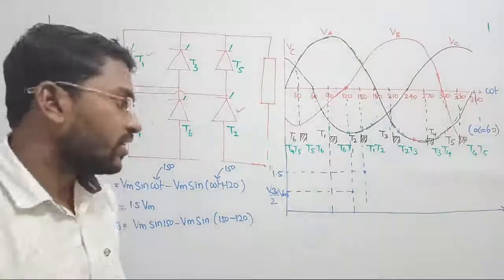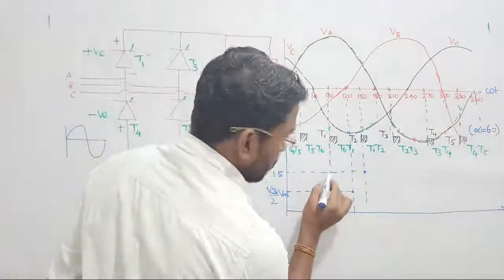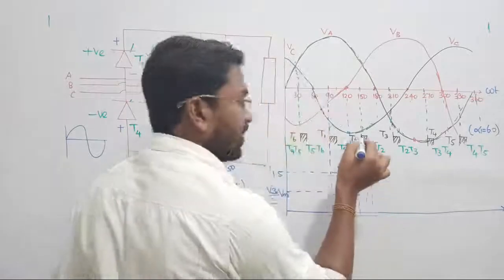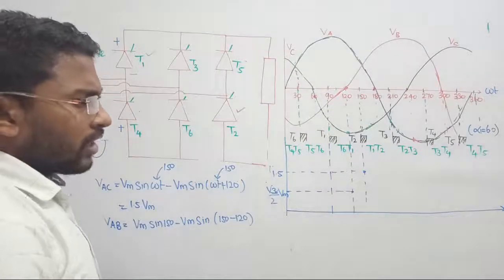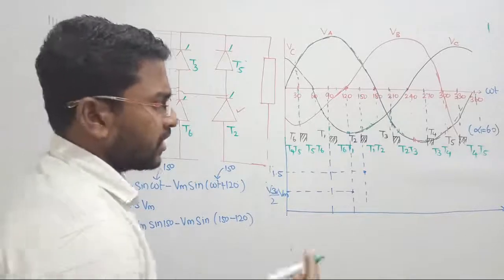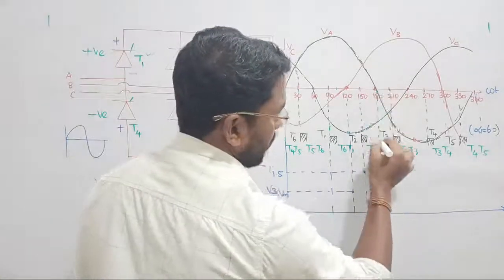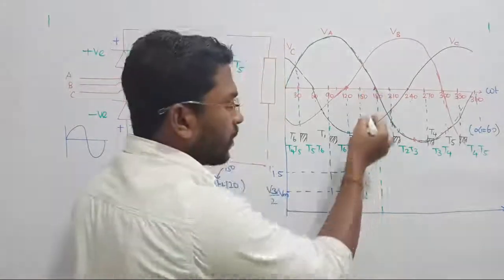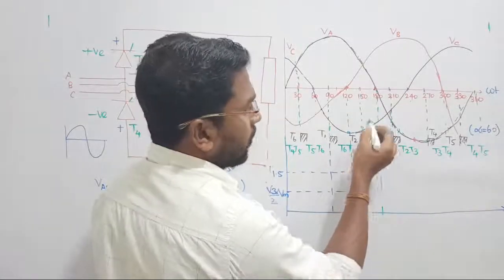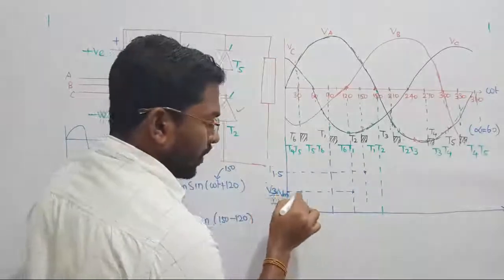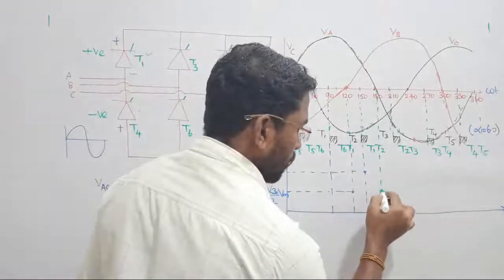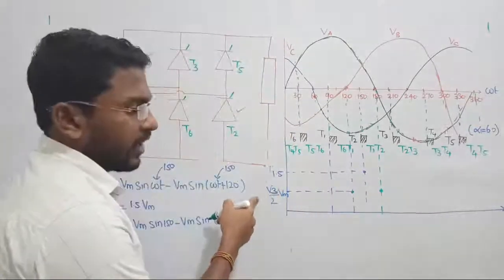Did you notice? Yes. So this value has been reduced to 0, and again there will be a hike, right? So let us continue. So the waveform you found will come back at the same place. See there, so what will come next? Intermediate point. Let us select 180. At 150 we are triggering the thyristor. In between 150 and 210 we have an intermediate point, that is 180. What will the value be there? Exactly we are going to get the same, that is 0.866 only.